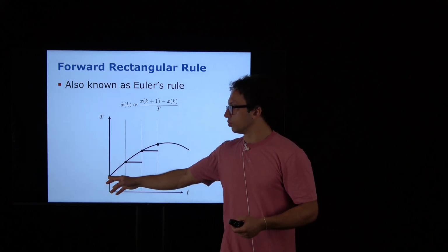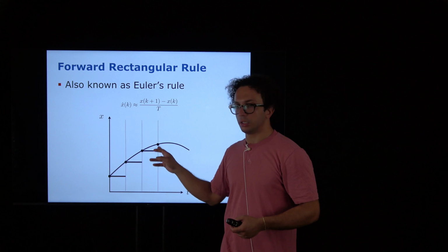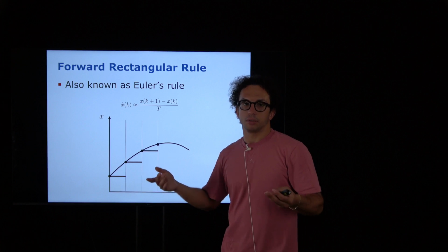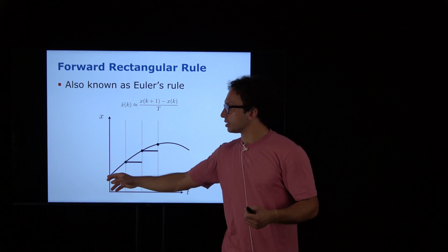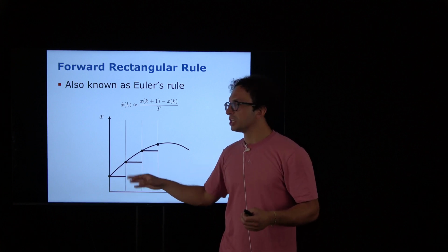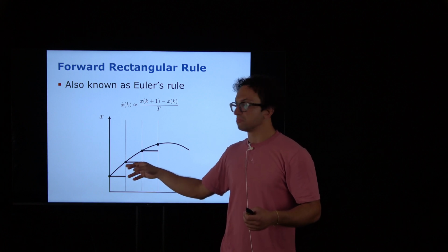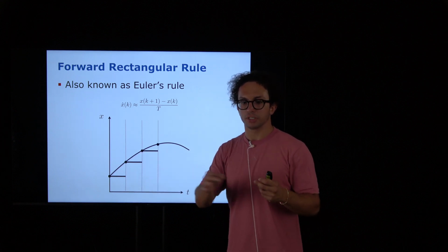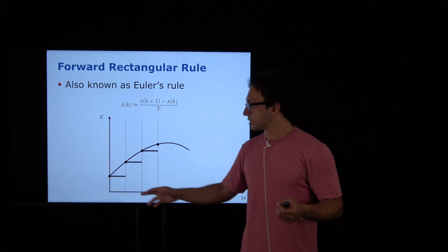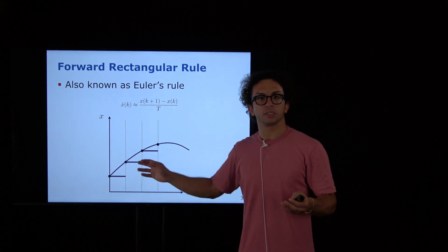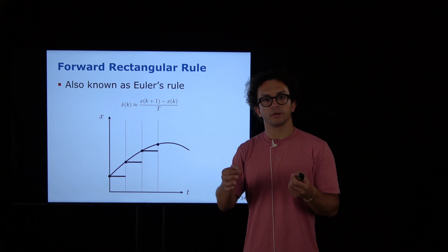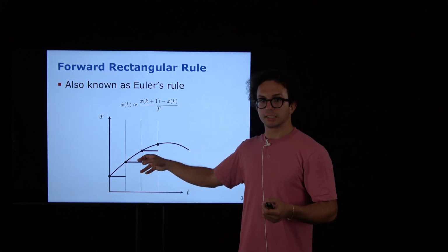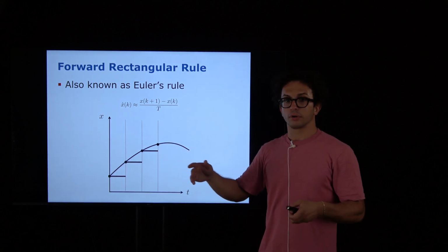We can only see the value of this thing that we're measuring at certain instances of time. So we assume that in the meanwhile, it's not changing. If this sampling time is 1 second, it means that the system is basically not doing anything for 1 second. It reaches the state and it stays there. And it reaches the state and it stays there. And so on and so forth.